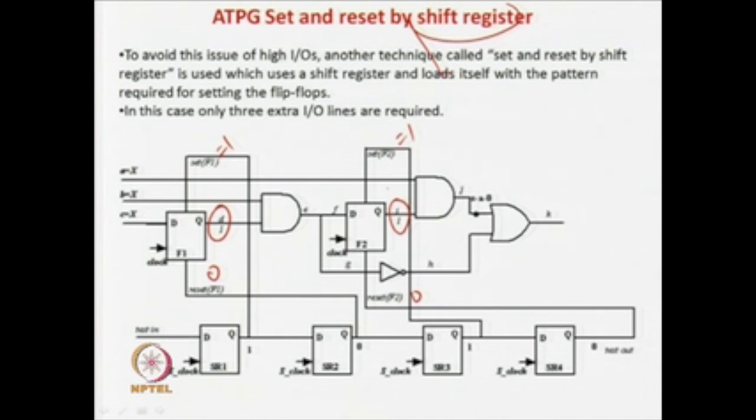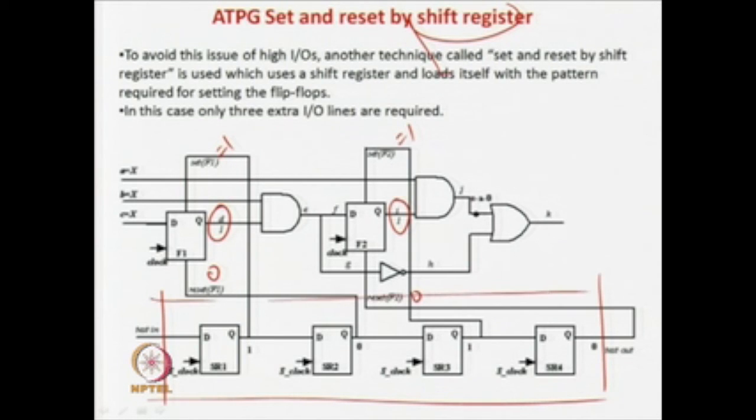Some people give the idea that you use what is called a shift register based technique. Now, what is a shift register based technique? In this case we just want to minimize the pinout. So, you will have a set of registers, a set of flip flops, connected in a shift register kind of thing. So, 1, 2, 3, 4. So, there are 4 pinouts.